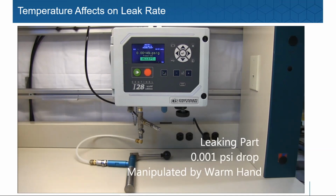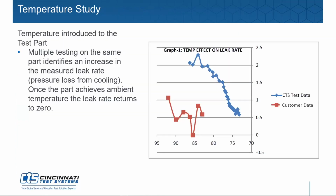Yep, absolutely. So here's another example of how temperature and pressure affect each other. We had a customer come to us and say, we are seeing a lot of variation in our leak testing. We're testing castings that are going through a washer system upstream, and they're coming in and we're seeing this variation, and we asked them, okay, what is the temperature you're testing at? And they said, well, it ranges anywhere from 95 degrees down to around atmosphere, 80 degrees.